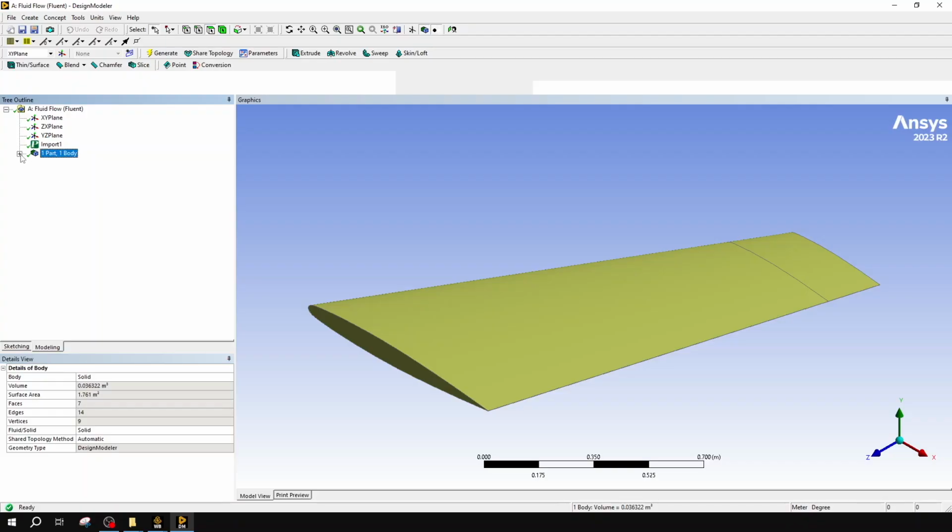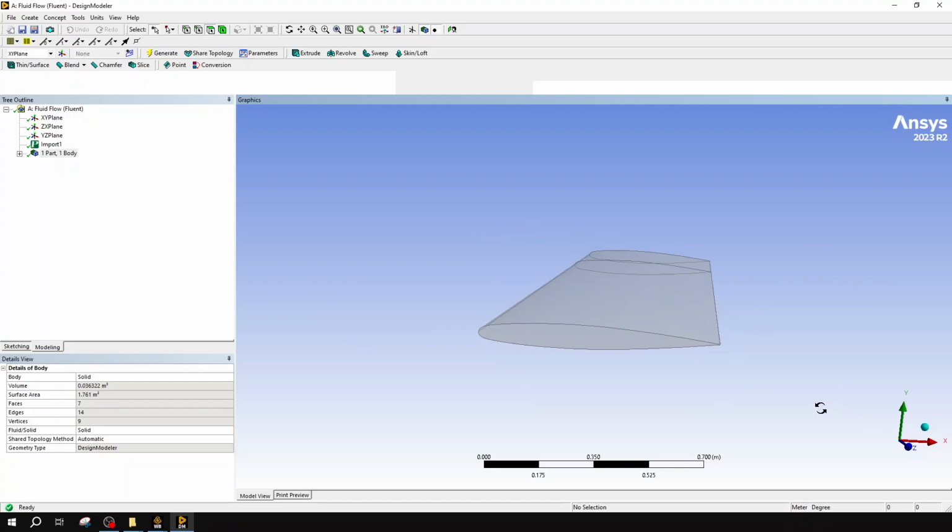So now that I got my wing in, we're interested in making a pseudo wind tunnel. So now I'm going to start sketching out my wind tunnel box for this program. It's a little, I'm going to say, funky when it comes to sketching. To actually start a sketch, I need to define up here which plane I want to sketch in. I'm going to want to do the XY plane, so I'm looking at my cross section this way. So it's already on the XY plane, pardon me.